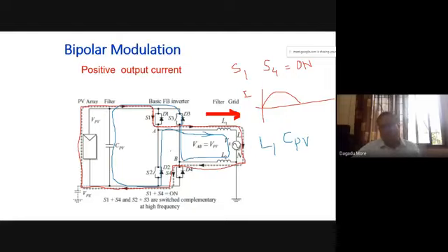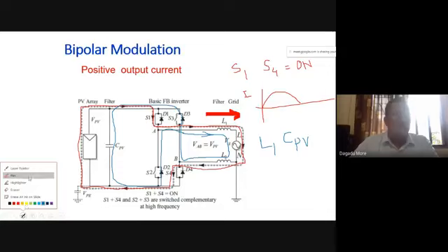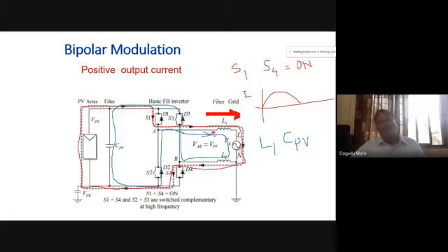And this we can call reactive power flow. This is actually an exchange of power between inductance and capacitance. Now the current will flow between these two, and this leads to a low power factor, and this is not advisable. The efficiency of the inverter will decrease.